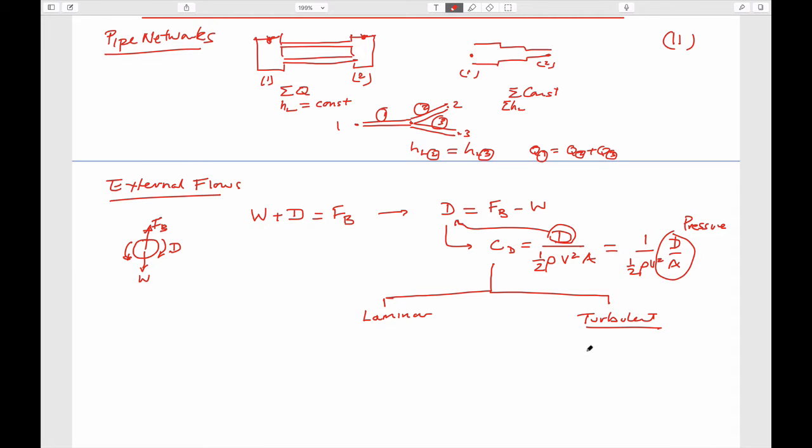So I guess you can always rewrite this as the drag is equal to the coefficient of drag multiplied by a half rho v squared A. And if you know what this is, or substitute into here, and you know what these other 2 components are, you can solve for the one unknown.